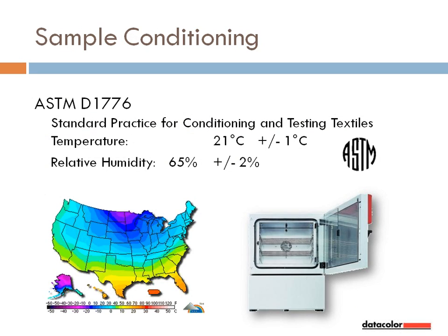Here are recommended practices for environmental conditioning of textile samples. Every object changes color with temperature. Many do the same with humidity changes. Colorants in coatings or embedded in plastic tend to be less sensitive to humidity. Paper, textile, powder, absorbent products, however, are far more sensitive.